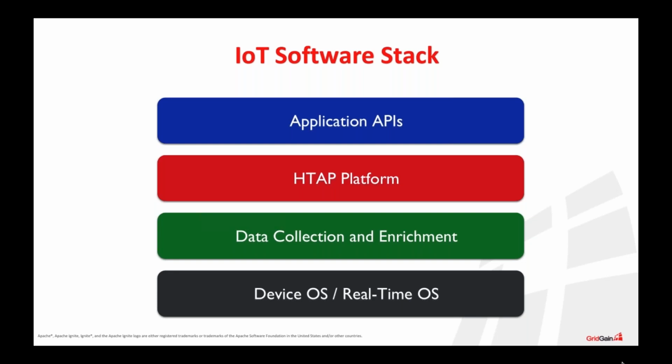But if you're going to deploy your software on MCUs, which are microcontrollers that don't have a lot of resources, powered by Cortex microprocessors and having, let's say, only around 1 megabyte of RAM and probably 2 megabytes of flash, then Linux is for sure not the case for you, and you have to find some other operating system.